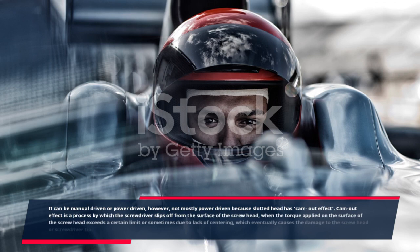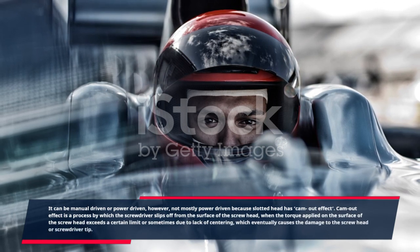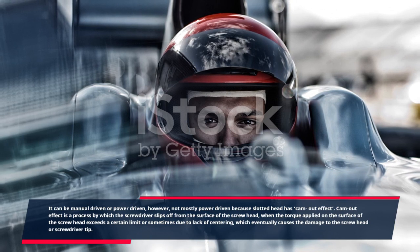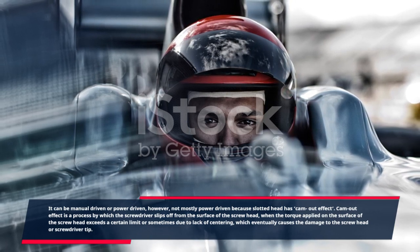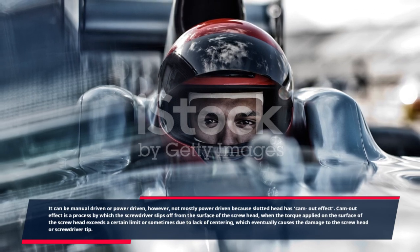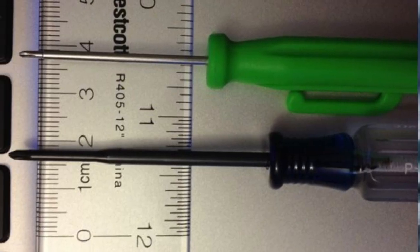Cam-out effect is a process by which the screwdriver slips off from the surface of the screw head, when the torque applied on the surface of the screw head exceeds a certain limit or sometimes due to lack of centering, which eventually causes damage to the screw head or screwdriver tip.